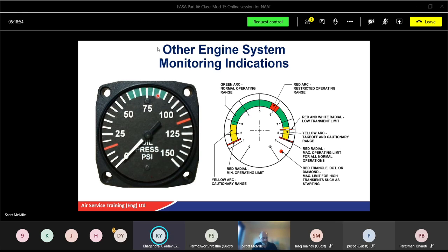If we've got the direct pressure indicator, we've looked at the graph, we found the index number, we then have to set the gauge. So how do we set the gauge? Knob. Yeah, so just turn the knob. That's it. That's all we do. What might you have to take into consideration when you're finding an index number?